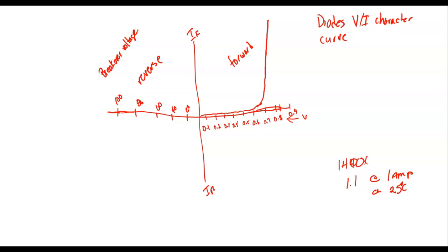That makes sense. They're all going to break sooner or later, and you can tell right off the bat that's not good. So on this side, we'll start over here. This would be leakage current. It's going to be a little more, and then somewhere along, depending on the rating, this is going to break over. For a regular diode, this is bad, because if you ever break it over in the reverse direction, odds are a standard diode is damaged. Now, we're going to look at a diode next week that is designed to operate in this region, in the reverse breakover voltage.